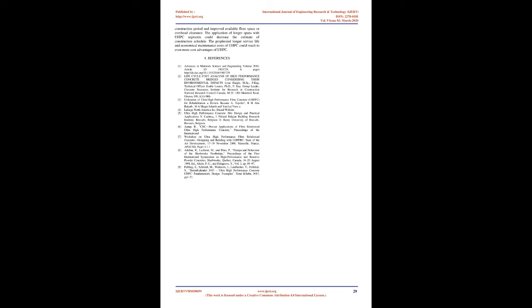Materials of varying particle sizes are used to accommodate the near-perfect dense mixture. Constituents like nanosilica, silica fume, rice husk ash, fly ash, fine aggregate of different sizes, and coarse aggregate of well gradation are employed to excel the mixture.